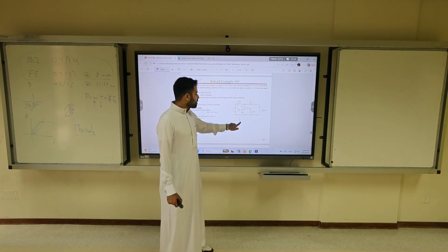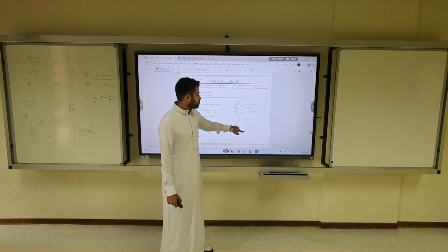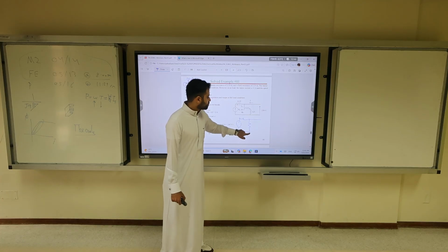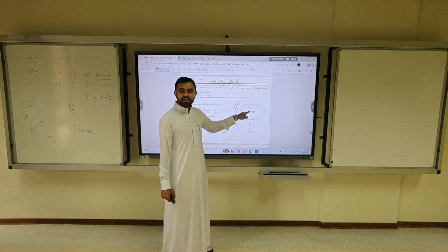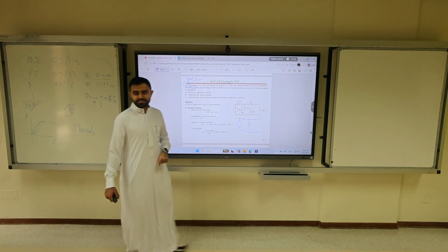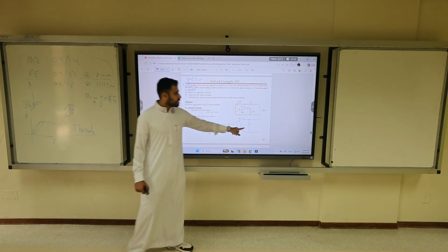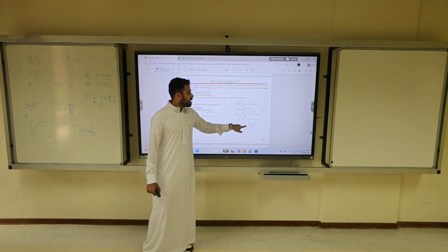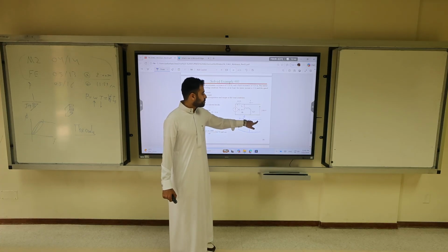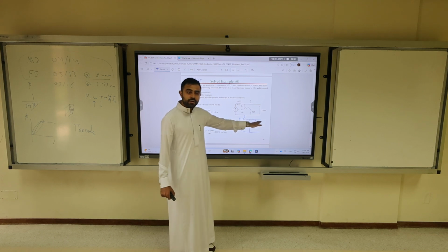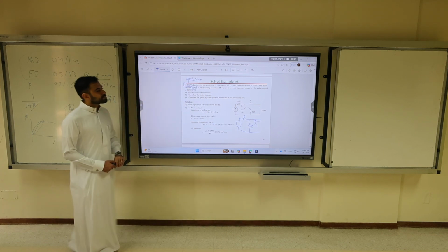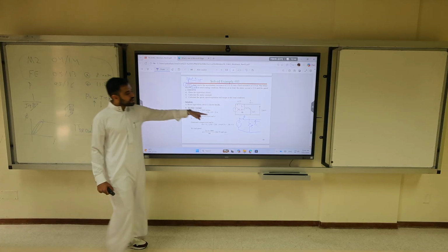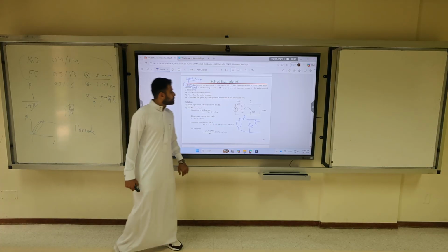In EE360 you can draw this circuit. Here they're adding an inductor for the transient. This is also a correct circuit. This is 250 volts, this is RF, this is RA. Is it a motor or generator? Motor, so the power comes from the supply. So draw the equivalent circuit. This is the EE360 equivalent circuit.